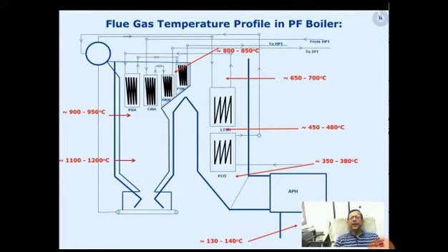That means if I consider a condition where the carbon finally meets with the oxygen, let us say here, in this area the temperature is less than 400 degrees centigrade. Therefore, the carbon is not going to take part in combustion. There will be no combustion of this carbon.